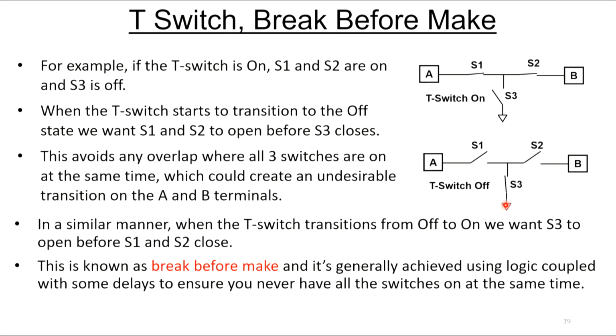And that could make the transition very messy, or a very undesirable transition from on to off or off to on. So what the break before make does is it makes sure that we open switches before we close the other switches. So we never have all three switches on at the same time. You've probably heard this term many times before.